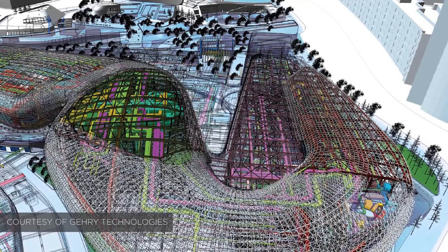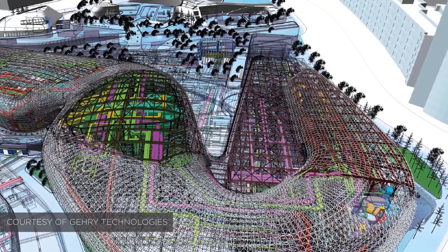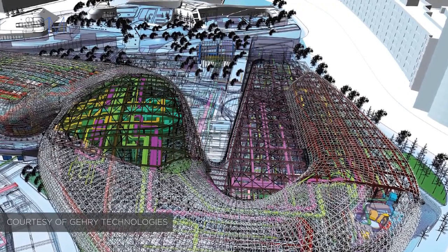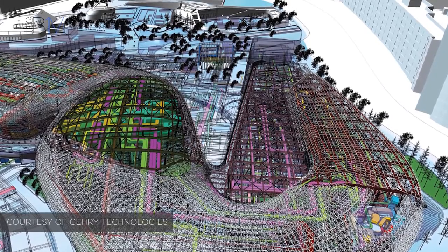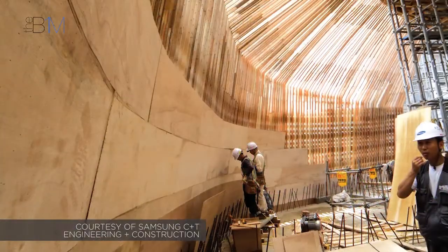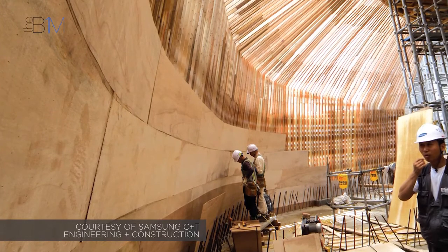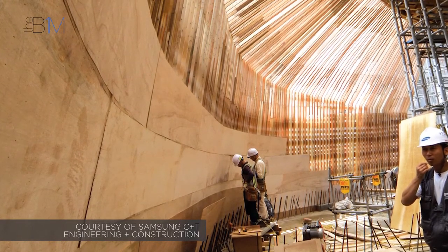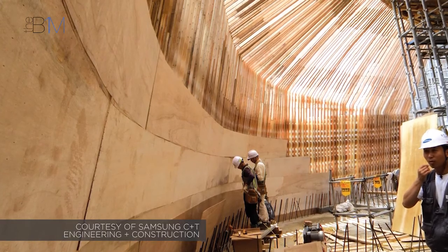Forming the unique annex buildings in reinforced concrete demanded highly accurate construction information from the design teams. The graphical information models were sliced every 30 centimetres. That cross-sectional information was then passed to the form workers who used it to form the complex reinforced concrete shapes. Despite having access to reliable and clash-resolved information in the graphical models, this formwork process was extremely laborious and considerably more expensive than conventional approaches.